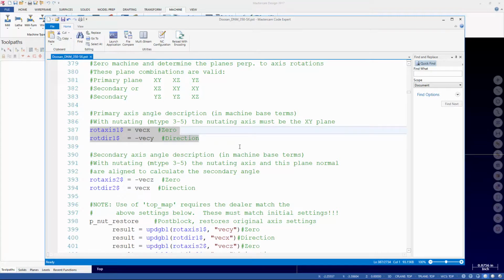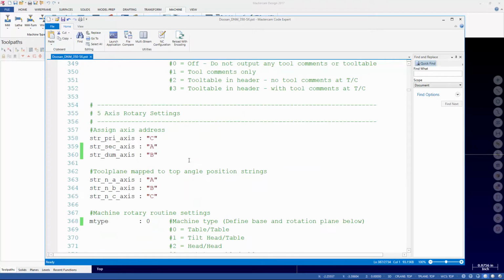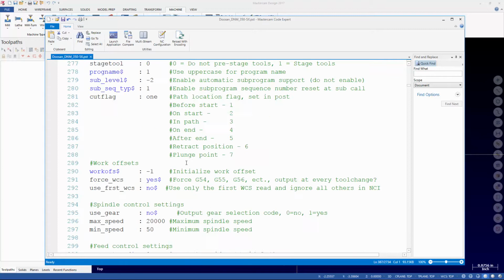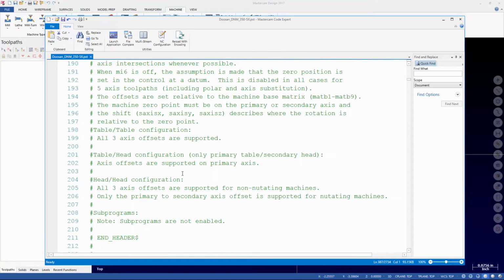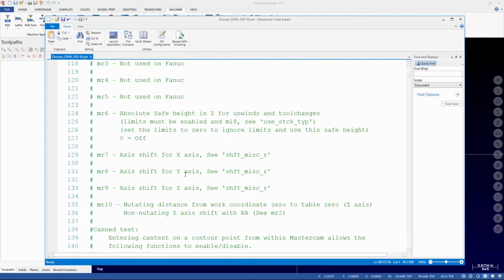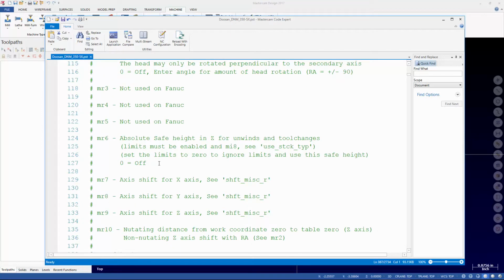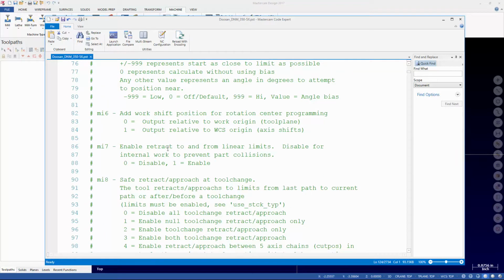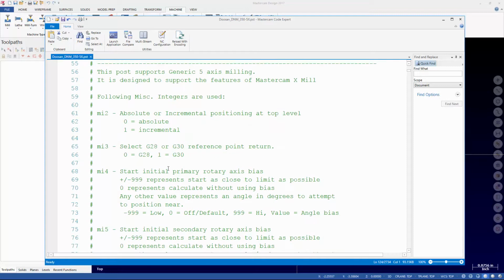Does this make it output retract? What do you mean this? You're talking about the safe retract? Safe retract actually outputs a Z coordinate as a Z value relative to your current work offset. It does not change between the G98 values or G28.